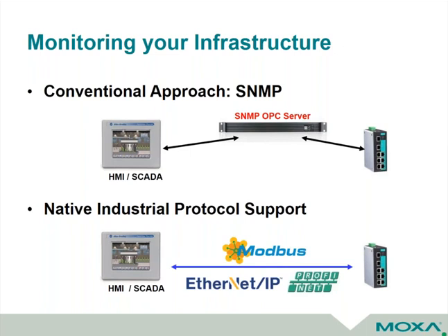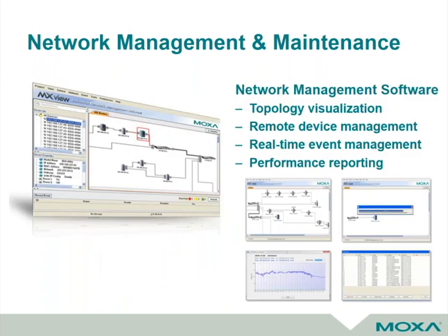That could be as simple as an overload condition that caused a breaker to trip and caused a VFD to go offline, and when the VFD goes offline, losing that link status on the switch. So some really cool stuff here, and I hope if you're not using that you'll think about it.